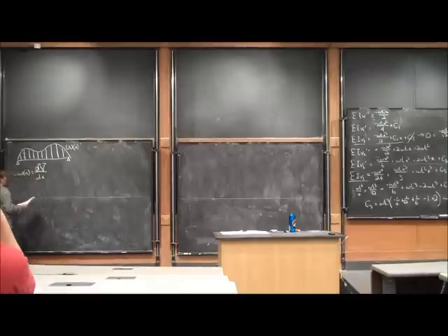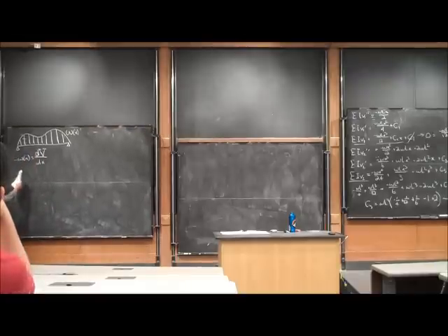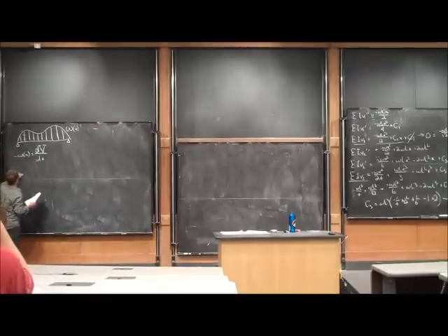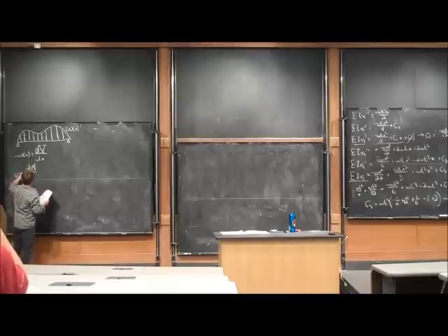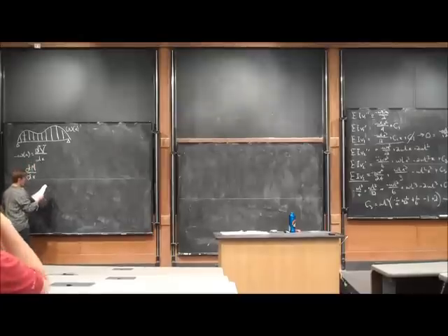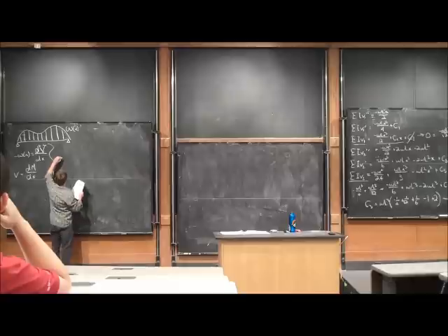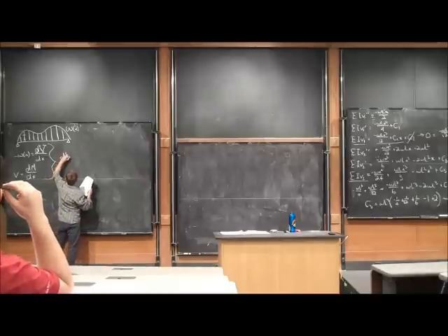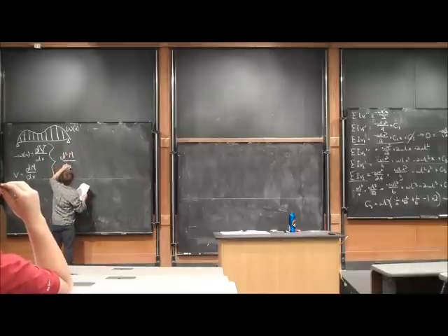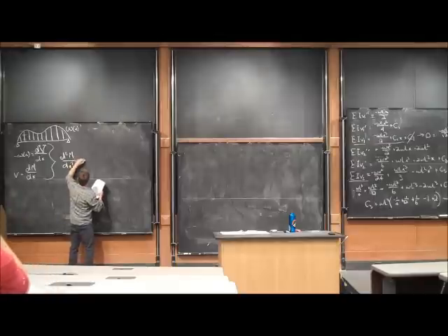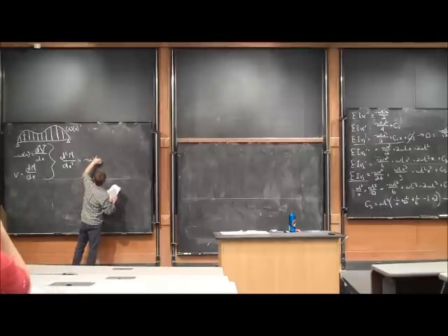And we can also recall that our shear was equal to the derivative of the moment equation. And if we put all this together, we can see that the moment, if we take the derivative of it twice, is going to be equal to the negative of the loading function.